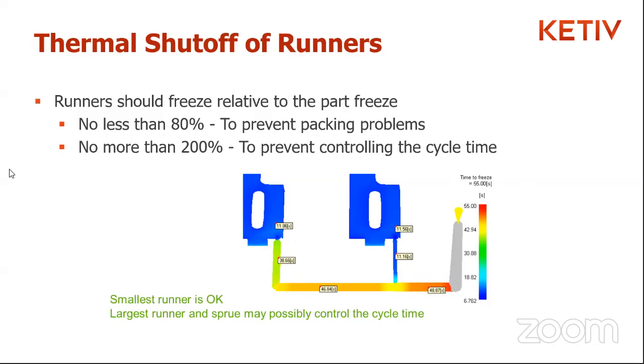Now, similarly, you're looking at how quickly the runners are freezing with respect to the part. You don't want that to be a barrier to having identical molded parts.